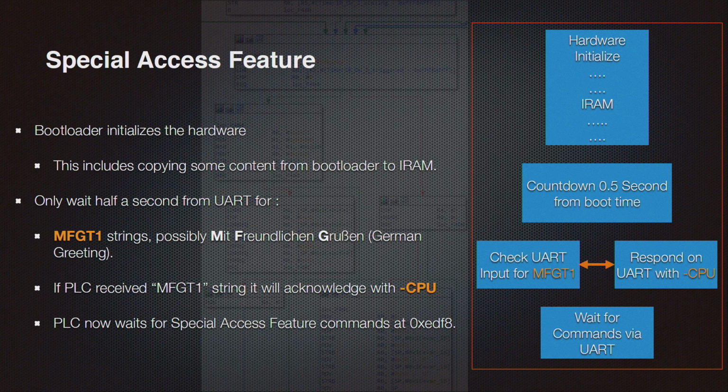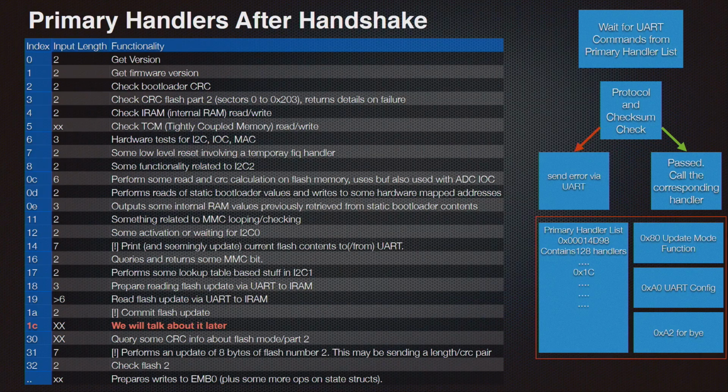And if the PLC actually receives this string via a UART in the first half a second of boot time, it would send you back the acknowledgement of -CPU. So if you get this back, you would be sure that this handshake has been performed and that you actually have this functionality on the bootloader itself. And then after this initial handshake has been done, the bootloader will enter a specific parsing loop of commands that you can send it. We have different commands that we identified.